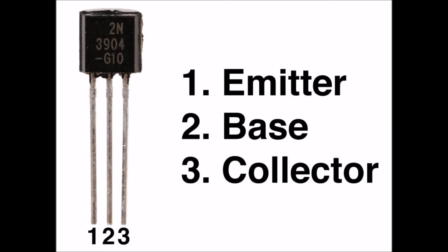Collector current versus base current. Figure 22.6 is a graph of the way the collector current, IC, changes in a typical bipolar transistor as the base current changes. We can see some points along the IC versus IB curve at which a transistor won't provide any current amplification.